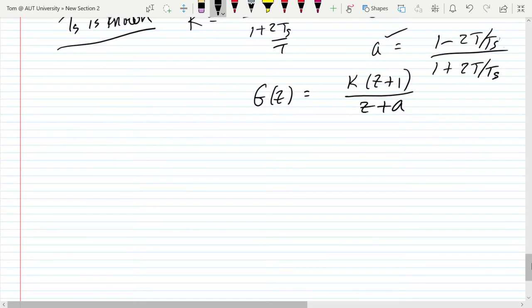But how does that help me in getting a digital filter? So this is like the first stage: I convert from G of s to G of z, and I do it with the bilinear transform because it gives me more accurate results. The other thing is, if you have a transfer function that's stable in analog, and most of them are if you're designing something, then you expect it to be stable in the digital domain. Otherwise, if it's not stable, it's pretty useless.